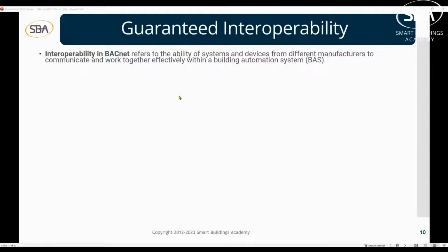Now, since the 90s, especially throughout the 2000s, the BACnet industry really got serious about, we need interoperability to work. We need everybody to be on the same page. If you say you're BACnet compliant, several things have to be true. And we looked earlier at the things that have to be true: the who is, I am, who has, I have, device discovery, device communication, being able to share information back and forth through token passing, things like that.